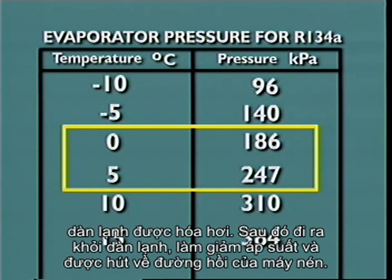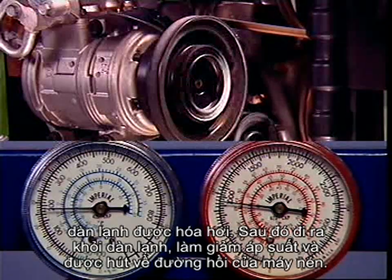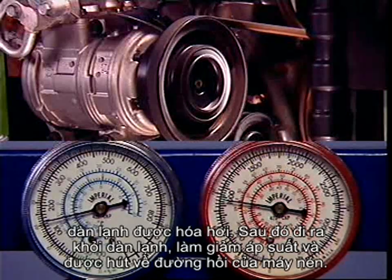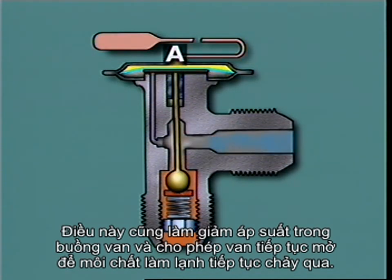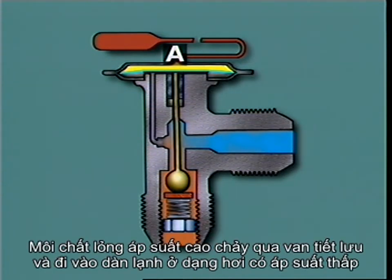before it leaves. When the compressor switches on, the suction from the compressor removes refrigerant vapor from the evaporator and lowers its pressure. This reduces the pressure in chamber B and allows the pressure in chamber A to move the valve away from its seat by the action of the diaphragm. High-pressure liquid flows through the orifice and enters the evaporator as a low-pressure liquid.